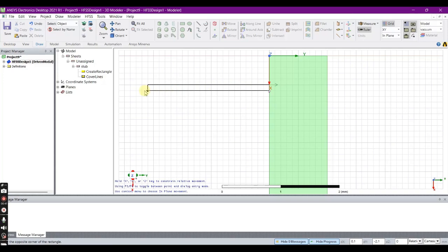And then the width of the finger is 0.3 mm. So on the x axis it is 0.3 mm, and on the y axis its length is 10.2 mm. So this is in the negative y direction. I am taking minus 10.2, and I am not applying any kind of thickness to the conducting portion. So it will remain 0.